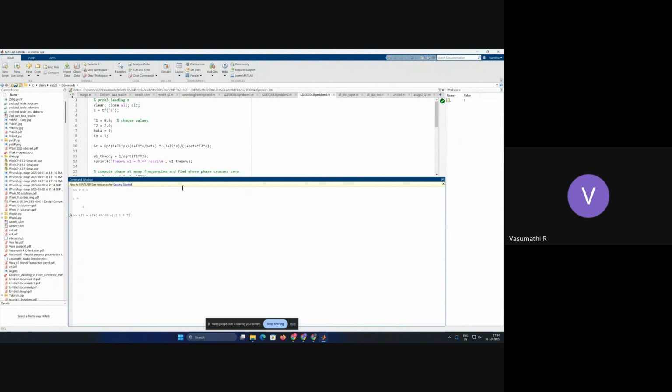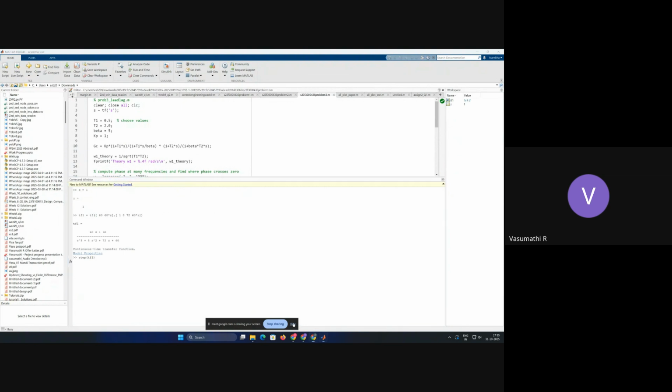I'm writing the closed loop transfer function into z. This is my entire transfer function. Now I want to see the step response of the system, because I want to see the peak overshoot, right? So the command to do this is step of transfer function 1. Getting generated.